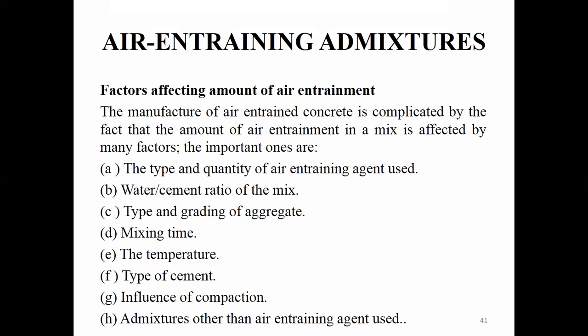Next, we are going to discuss the gradation. Uniform gradation should be carried out because it influences the quantity of the air entrainment. So grading of aggregate should be ensured while making air entrained concrete. Next, we are going to discuss the mixing time. The amount of air entrainment is found to increase with the mixing time up to a certain time, and after that prolonged mixing will reduce the air entrainment.